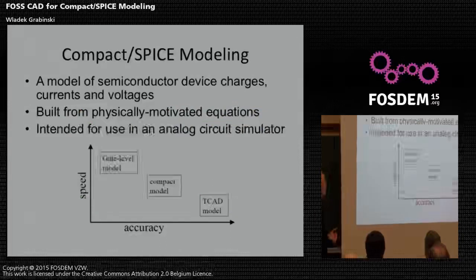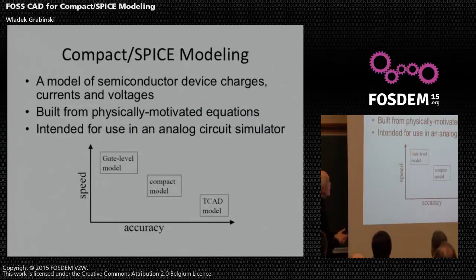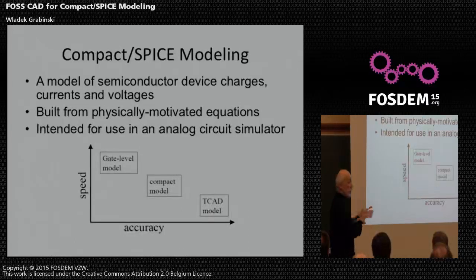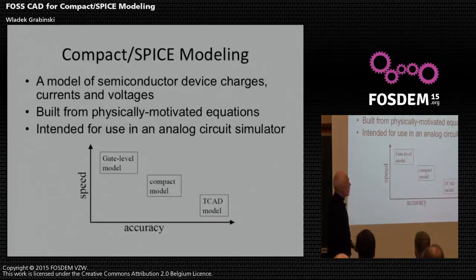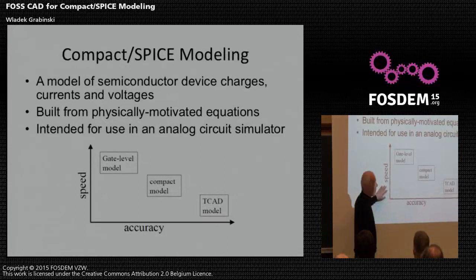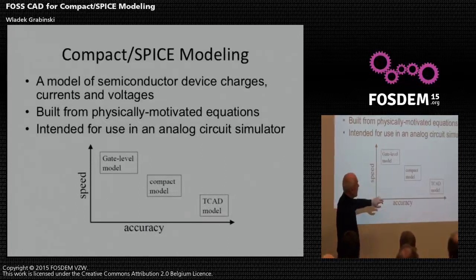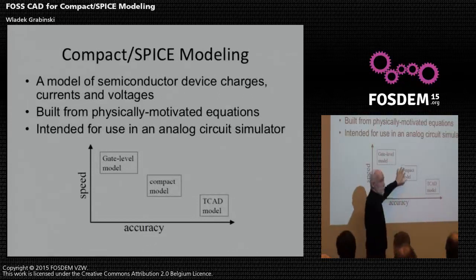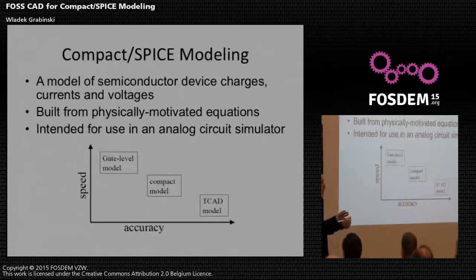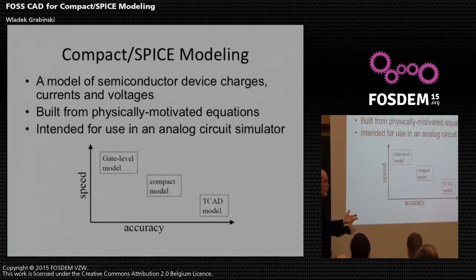What is a compact model? It's a representation of semiconductor devices, their charges, currents, and voltages. We are trying to go from very complex numerical simulation to a simple analytical representation, preserving also device physics. In terms of accuracy, TCAD tools, these two tools I already mentioned, and of course the huge development of commercial tools, provide high accuracy, but they are very slow because you have to solve a 2D grid to calculate device charges, currents, and voltages. Compact models are much simpler because we are trying to develop a simpler equation which gives you or predicts the behavior of your device.